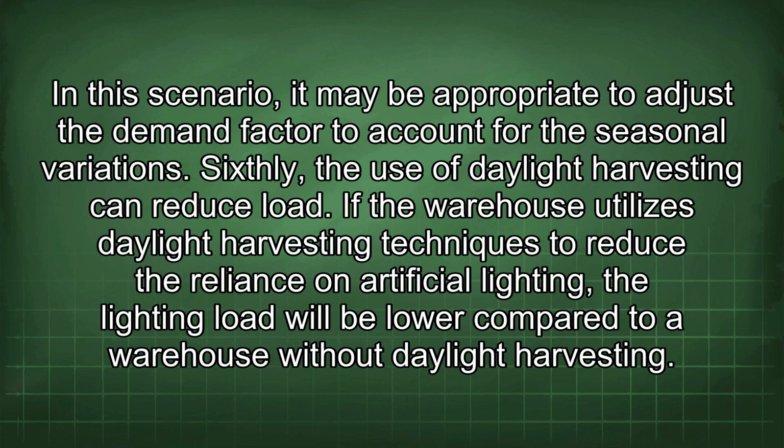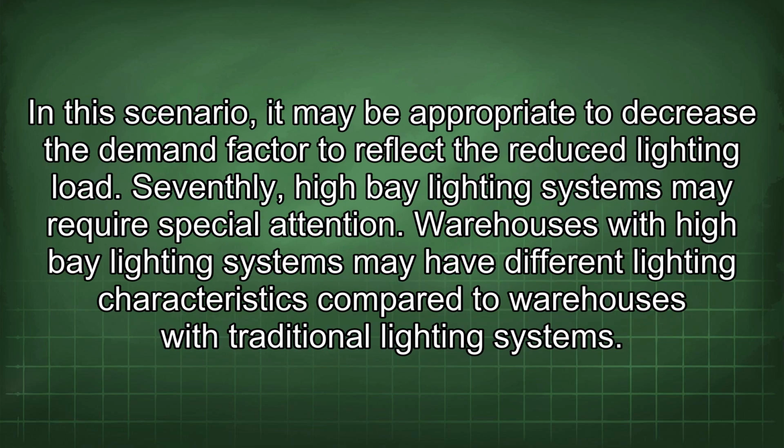Sixthly, the use of daylight harvesting can reduce load. If the warehouse utilizes daylight harvesting techniques to reduce the reliance on artificial lighting, the lighting load will be lower compared to a warehouse without daylight harvesting. In this scenario, it may be appropriate to decrease the demand factor to reflect the reduced lighting load.